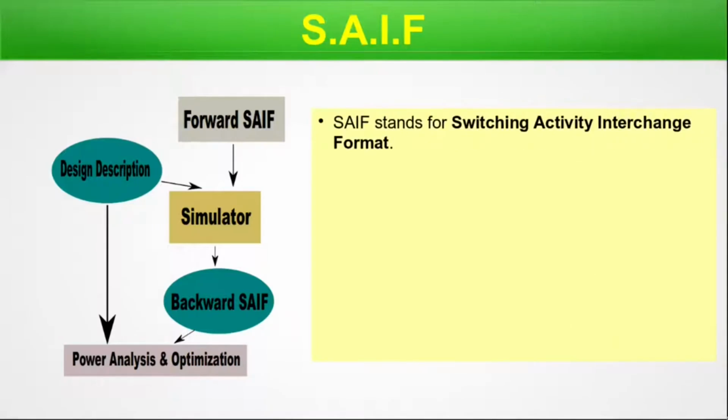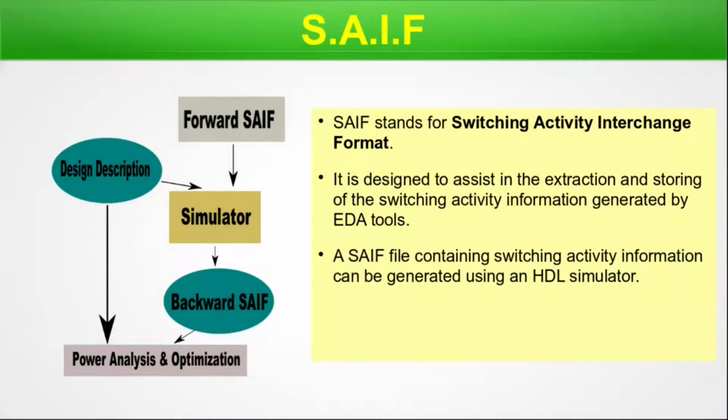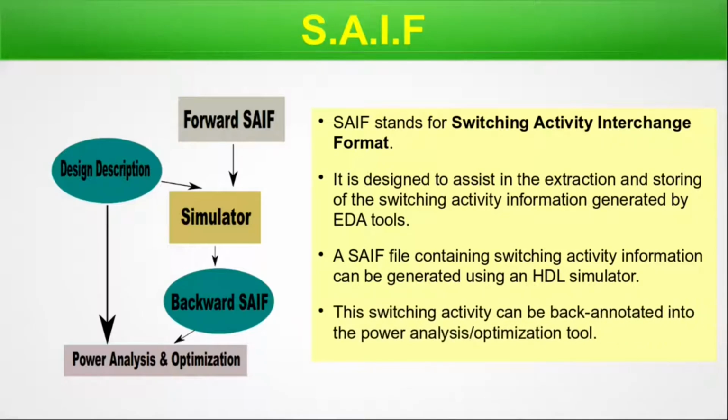SAIF stands for Switching Activity Interchange Format. It is designed to assist the extraction and storing of the switching activity information generated by EDA tools. A SAIF file containing switching activity information can be generated using an HDL simulator. This switching activity can be back annotated into the power analysis or optimization tool. So this is the overview of the SAIF. So let's move on to the next slide.